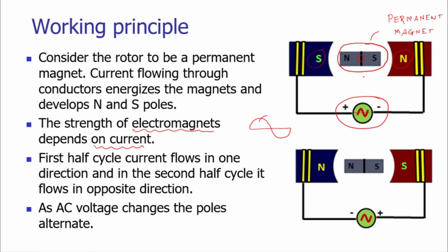In this situation, the north pole of the rotor magnet will get attracted towards the south pole and it will get oriented in the fashion shown on your screen. If we consider that this was the SN pole in its previous position, then when this half wave, that is positive towards this south pole, is energized and negative polarity is given to the north pole, what happens?